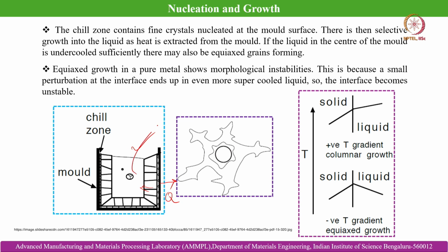So, this condition speaks of a positive thermal gradient, wherein the solid temperature is less at the interface. It grows towards the interface, and from the interface it increases within the liquid, which is suitable for columnar growth. So, you can relate it to this.